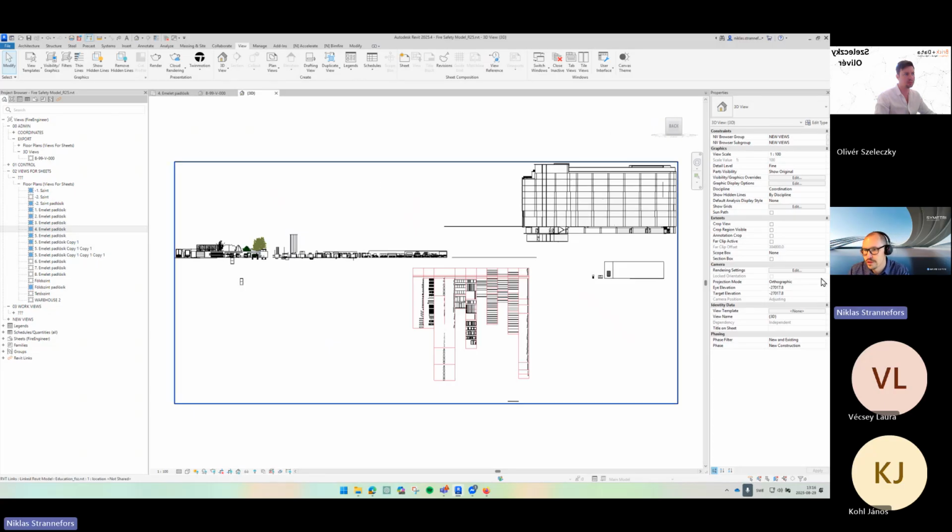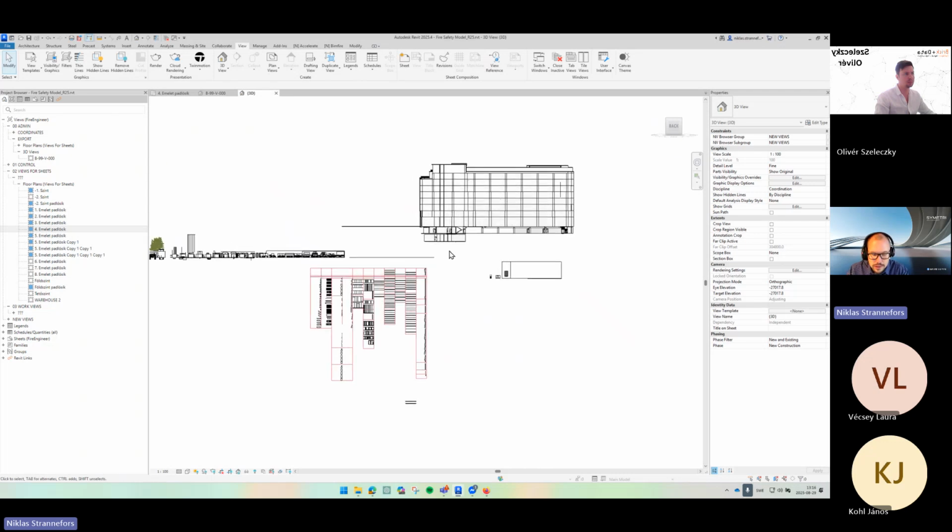And if you have a section box on, like this ticked, you can untick it and apply, and we'll see the entire thing. This is something I use quite often, and that is called temporary view properties. Down here, just to the right of the light bulb, you have the glasses, you have the light bulb, and then you have what looks like an old camera roll, in the very bottom of every view. We can enable this temporary view properties.